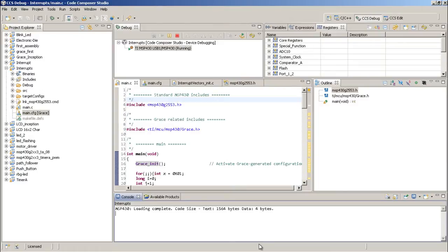If it is a hardware interrupt, the signal can be a rising edge, a falling edge, or a level trigger. If the signal is rising edge triggered, then the signal must go from level 0 to level 1, and if the interrupt is negative edge triggered or falling edge triggered, the signal has to go from high to low.